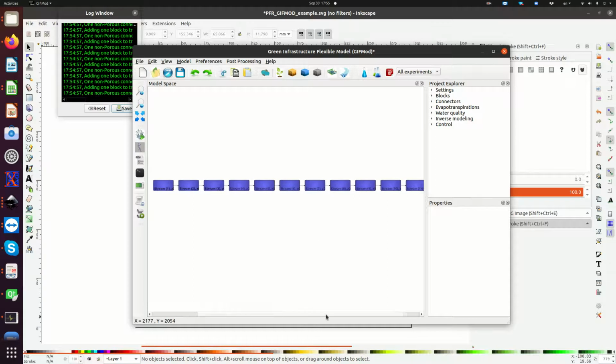So okay, so a few other things. So I'm going to first do the hydraulics. As I said, what I'm going to do is that I'll just essentially configure the model so that the flow is equal, and hydraulically we are under steady state condition. That means the flow going into and out of each of the blocks is the same, and that basically the volume of each of the segments, the volume of water or storage in each of the segments is not going to change with time.